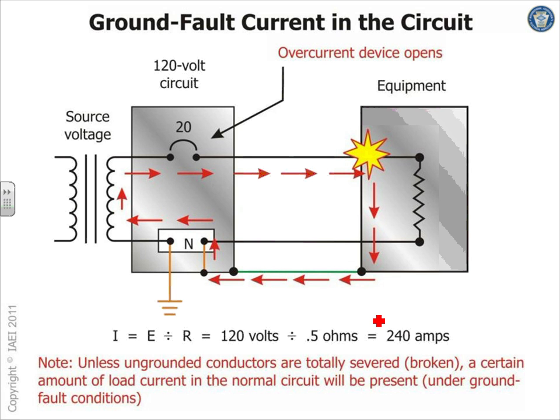I'll show you how the overcurrent protection device will see this amount of, look at this one, 250 amps coming out of a 20 amp circuit. How would that happen? That's for a very, very short amount of time, less than 3 cycles. Then it will see it and trip in less than 3 cycles, and by doing that, it prevents your building from burning and your people from being electrocuted. Any comments, guys? Any questions about that? Make sense? No, yes?